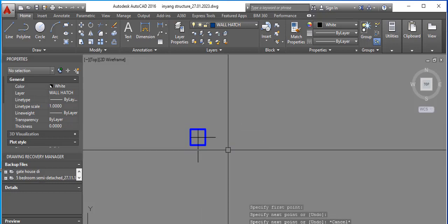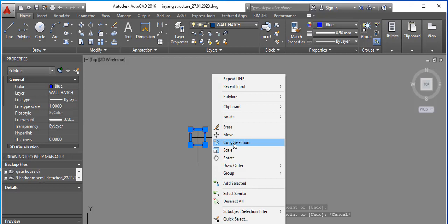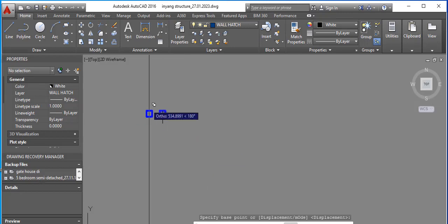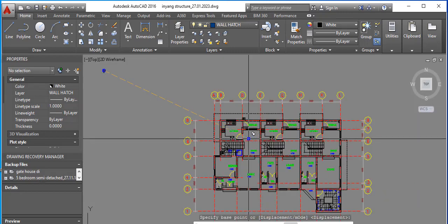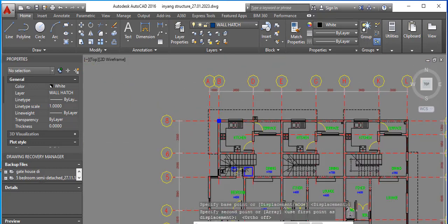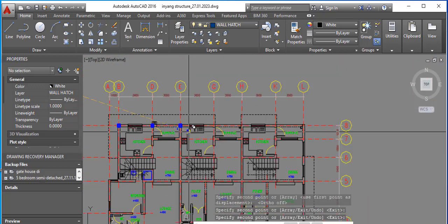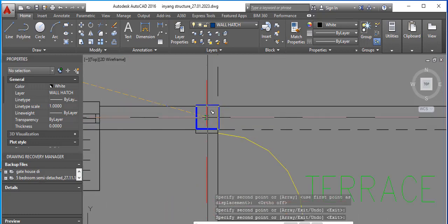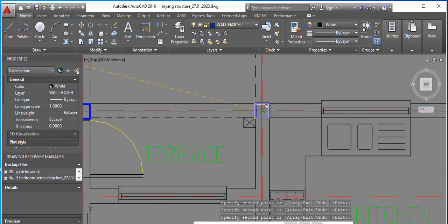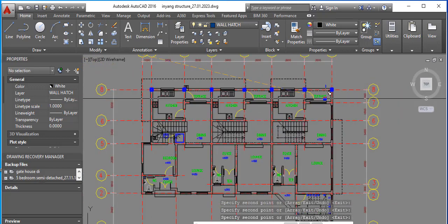So now we have gotten our column. The first thing you do is to copy your column, take your center line. We get our center line and we come here. We introduce it here at the places we hope to place our columns, starting with the ground floor. You start at the ground floor. Please pay attention, this is very important.